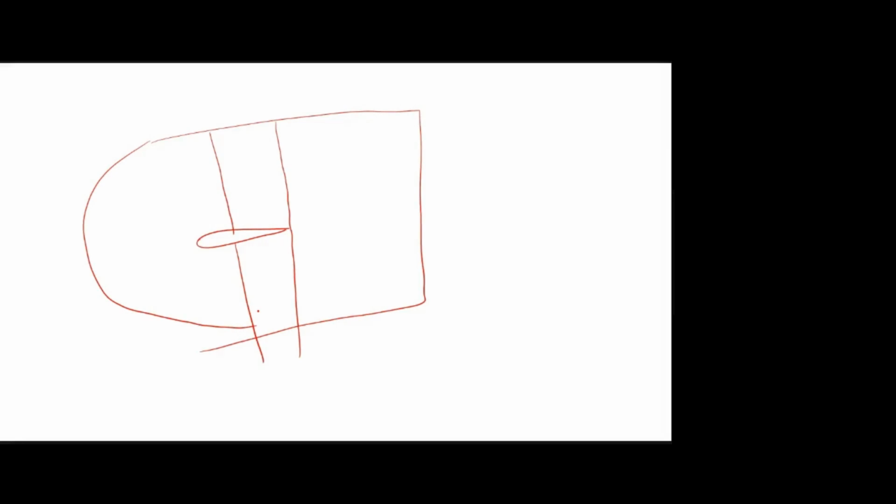If you have more than 6 phases, then some extra phases are there. So you need to click on each and every phase, find where it gets highlighted in the domain, and see which two phases highlight the same area. Once you identify that, you need to remove any one of the phases, save it and use it. That will rectify the problem.